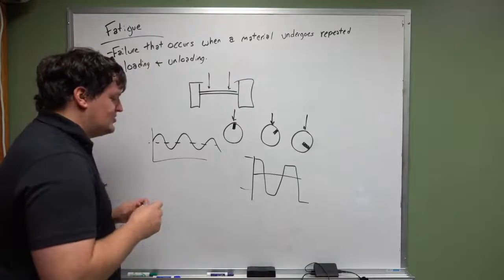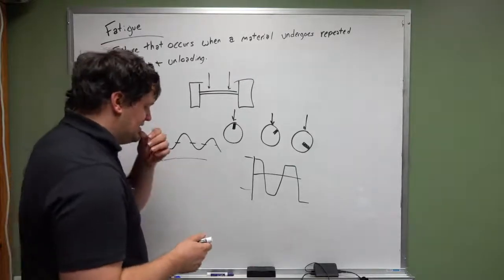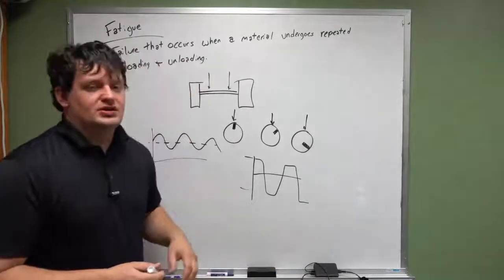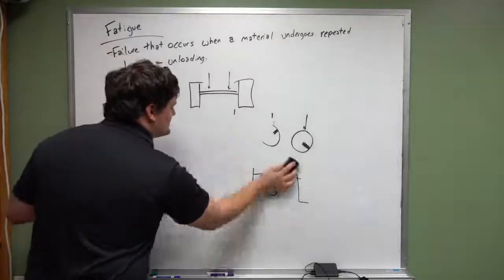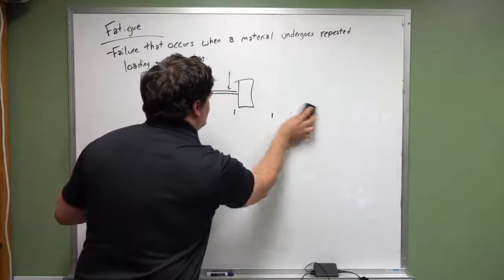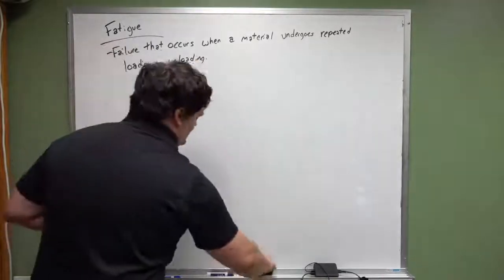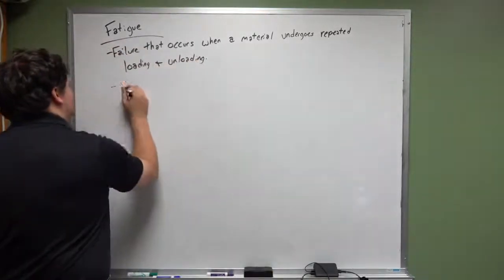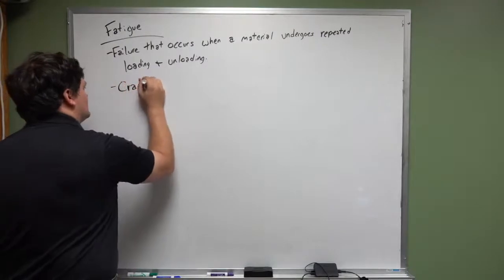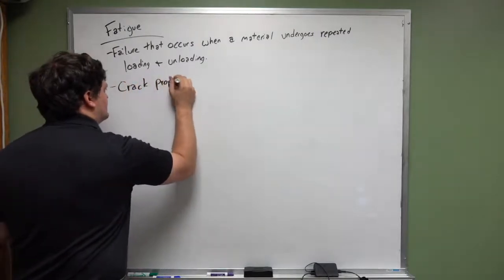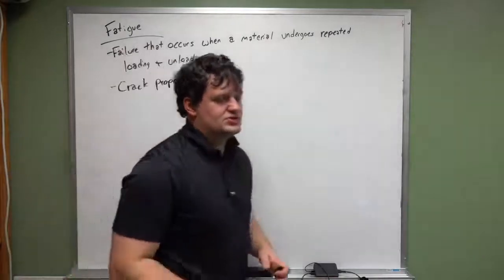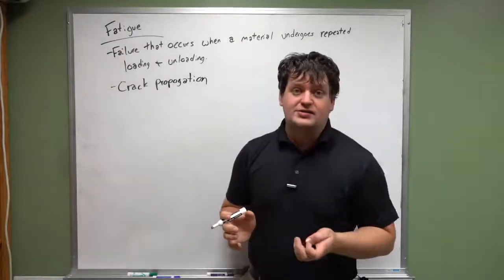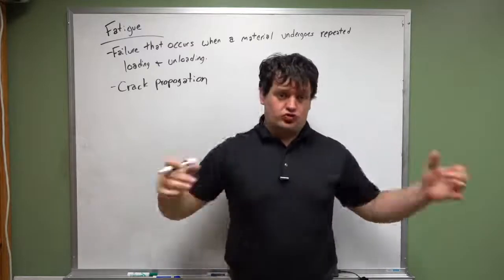But when it comes down to fatigue, this causes failure because, if you remember a concept that I introduced to you a few weeks ago, failure ultimately occurs because we assume that there are microscopic cracks in a material that grow.